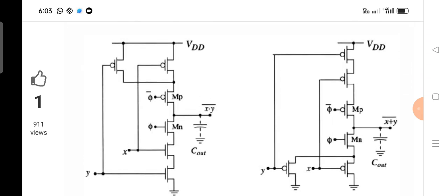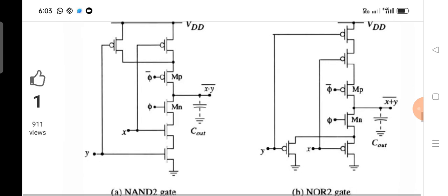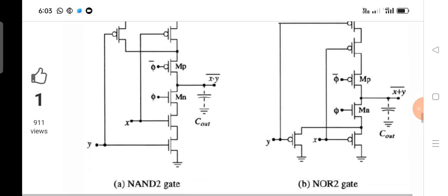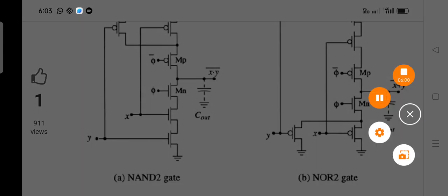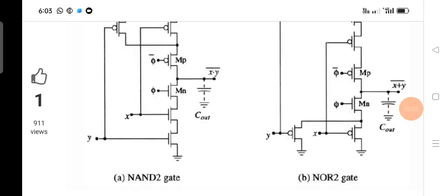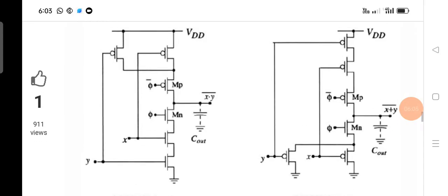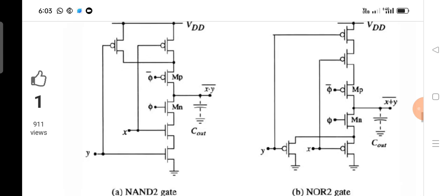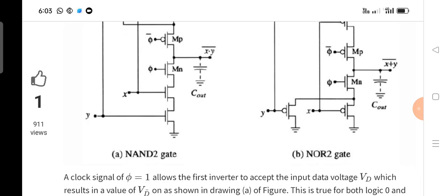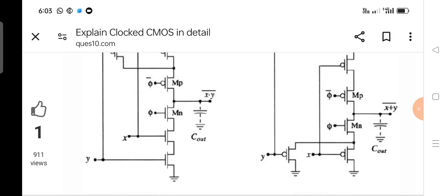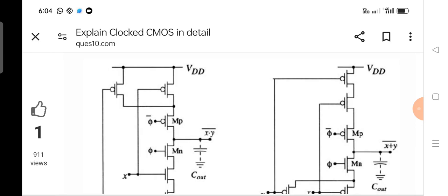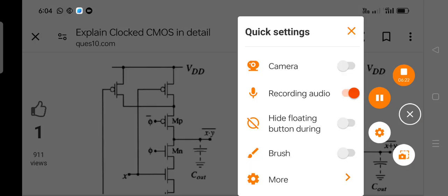Can anybody try to tell what is this one? Absolutely. These are the examples of NAND gate and NOR gate. You can observe if you want. We know very well from the previous concepts, I already said some keyword to you. What is that keyword? Absolutely, PAP. That means PMOS should be parallel in either AND or NAND configuration. Now you can observe that here two PMOS are there.